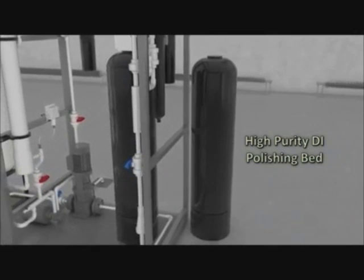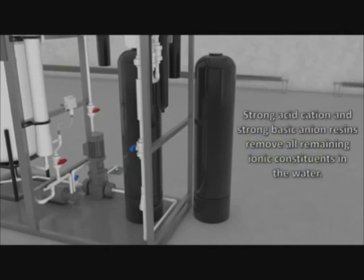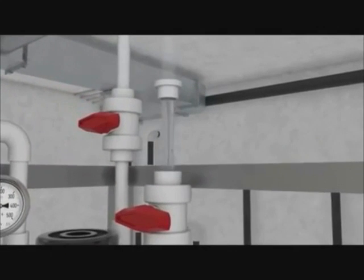If this is required, Process and Water implements a DI polishing bed containing strong acid cation and strong basic anion resins to remove all remaining ionic constituents in the water. The product water has been post-treated and is ready to be sent to the points of use.